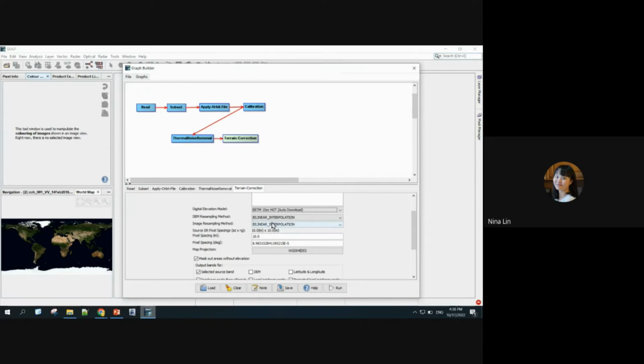And there is one very eye-catching phenomenon: when you do SLC to GRD conversion in Snap, between the different burst boundaries, you will be able to see the boundary. So there will be a line where you have an amplitude difference across the line.